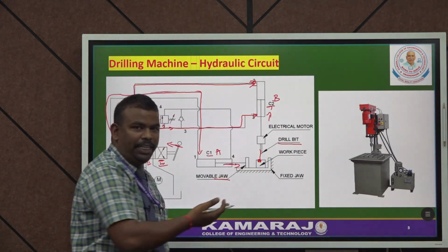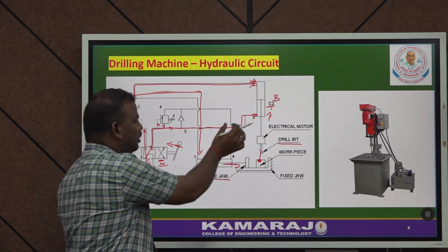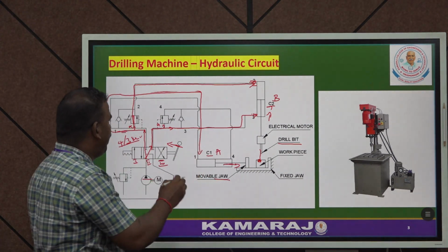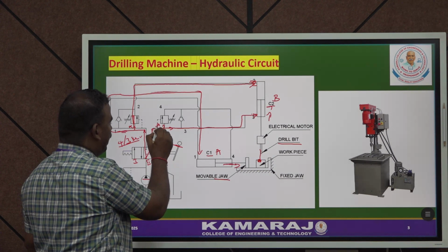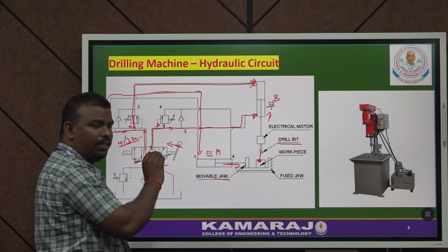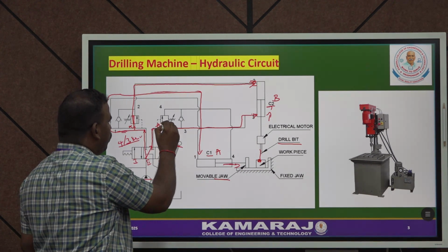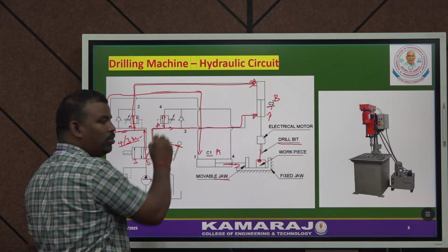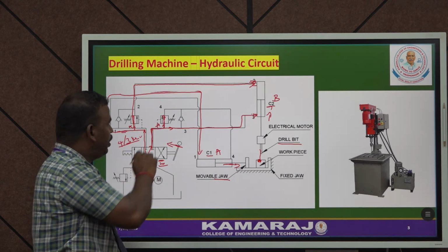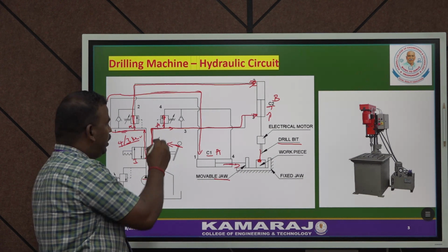Once the operation is completed, again some overpressure occurs. At the same time, this pilot operated valve is actuated. This pilot operator pushes the sequence valve, so now the pressure sequence valve also opens. Now the oil flows into the fourth pressure line, called the sequence line.